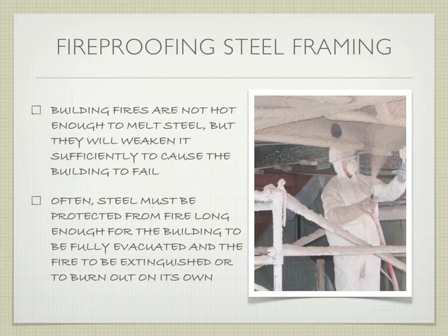It would depend, and I don't know what the fireproofing was made of in that particular building. My guess is that it was old enough to probably have asbestos in it, which probably is a good thing from a fire rating standpoint, as bad as it is from a breathing standpoint. So I don't know what the rating was on that particular piece. The ratings are going to vary depending on the type and the technology of the material and how they work together. So you'd have to go to the specific manufacturer and see what that material would be rated as.